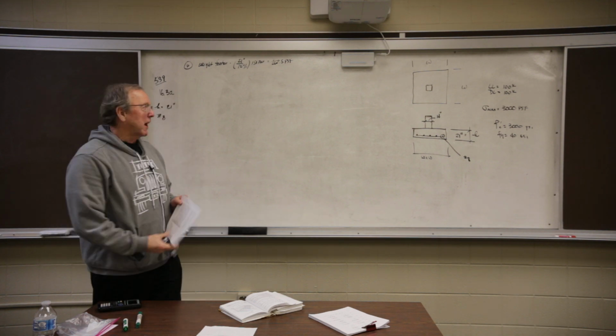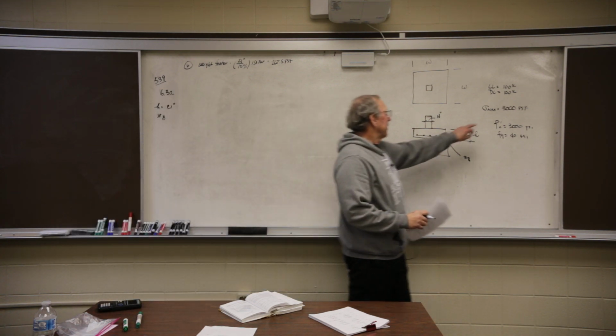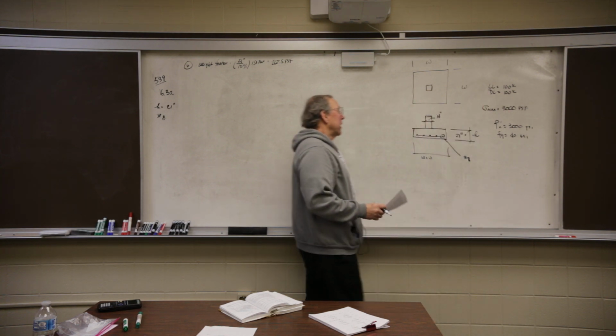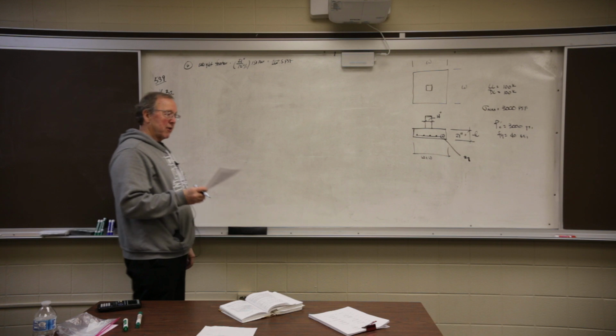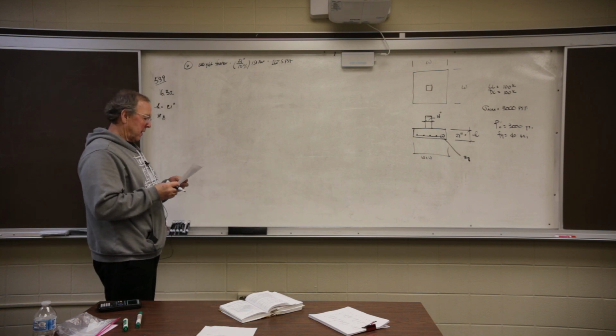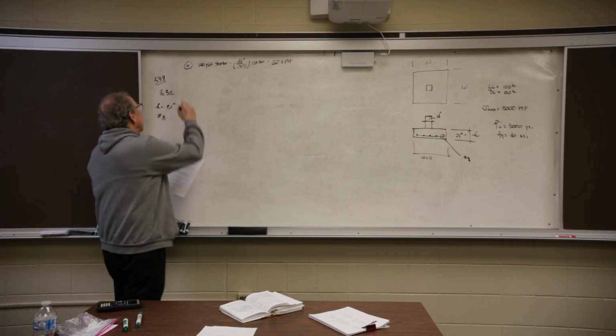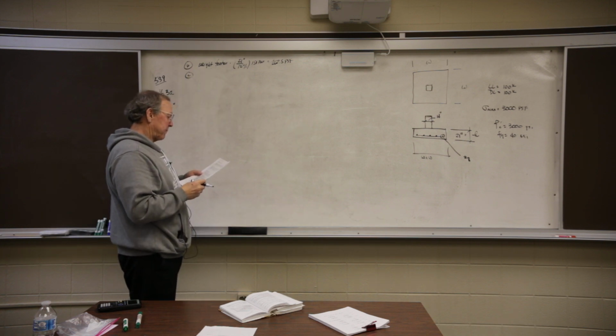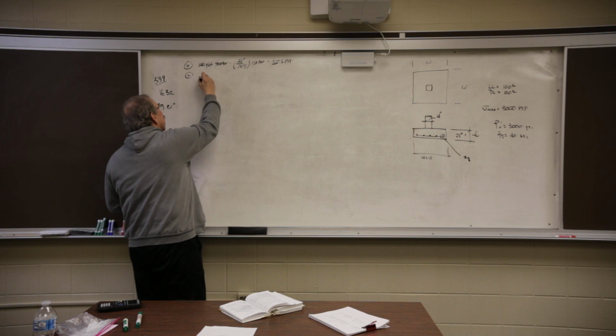The rest of the soil bearing capacity then is used to carry these loads. So I just got to make sure my footer is big enough to handle it. So the second step, B, C, was figure out the weight of the footer. The third step is find sigma net.